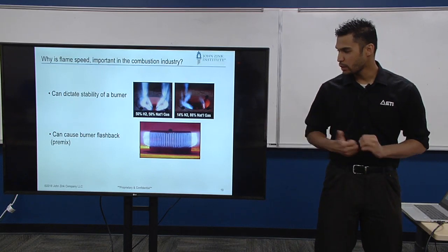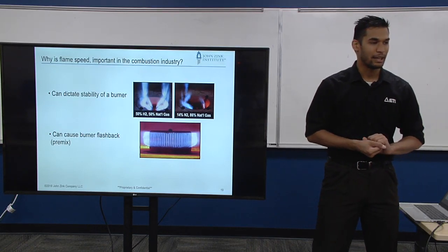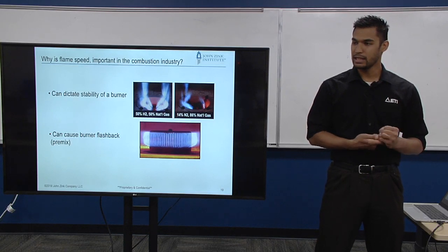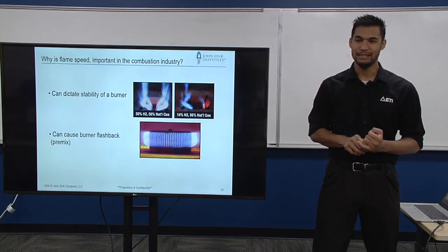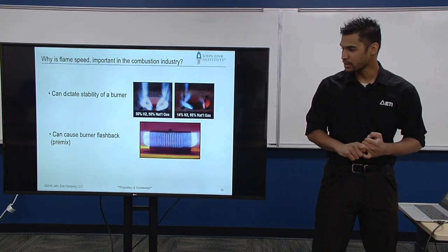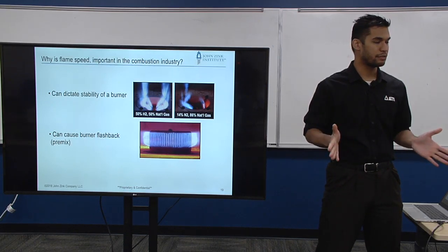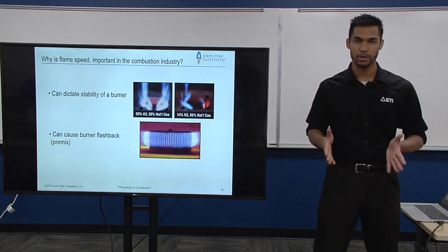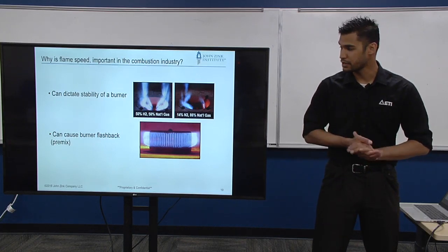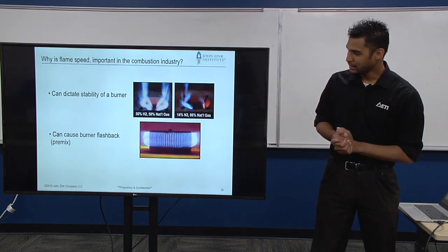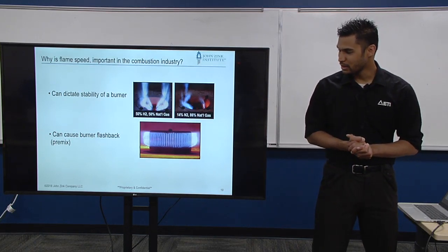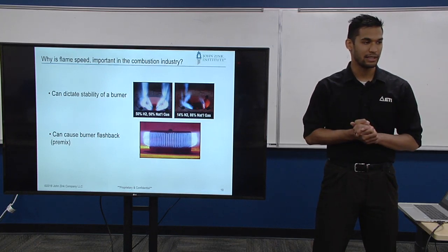What happens when you throw in a bunch of nitrogen? Okay, remember, natural gas is a little bit harder to burn. Can you burn nitrogen? No, it's inert. So I've totally thrown off the flame speed and the adiabatic flame temperature and the fuel properties and characteristics of this flame. And does that look symmetric, stable, and do you want to look into a heater and see something like that?